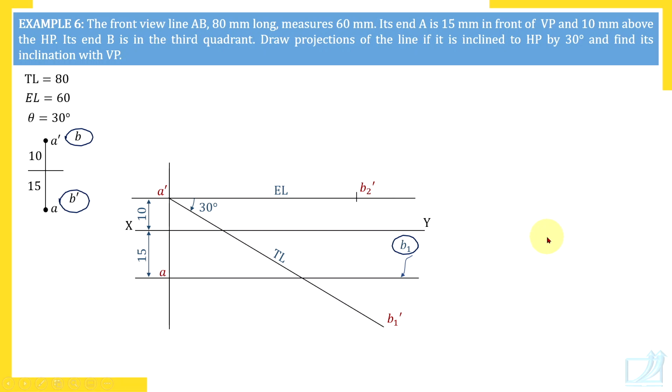So that first step is over. After this, horizontal vertical lines and rotation of the views. No measurements are required, because all required measurements are over here in our drawing. Now simply construction lines. So let's draw that. Through B1 dash, horizontal line. Which other point on this line? B dash. Through B1 dash, vertical line. Which other point on that line? B1. Top view of the same point. Here it is front view. So top view of the same point, that is B1.